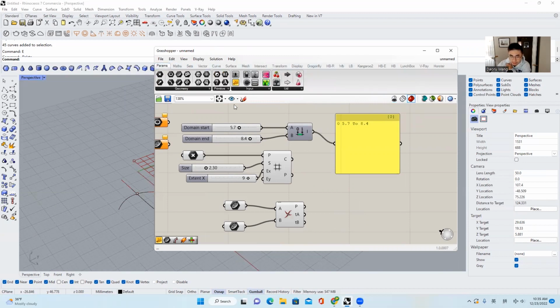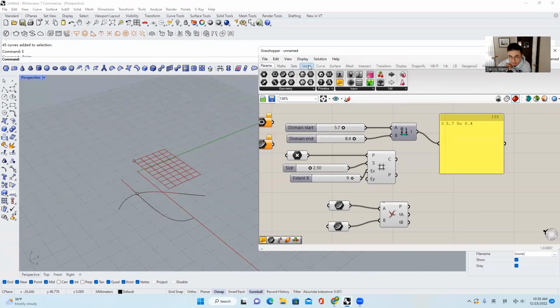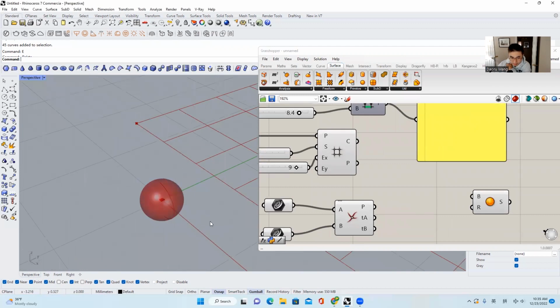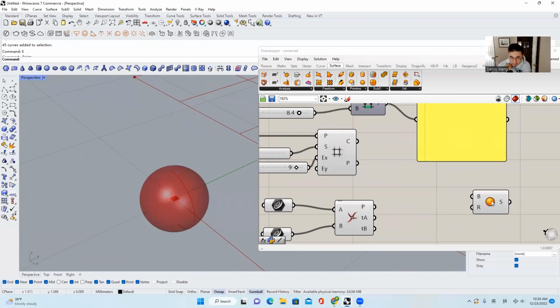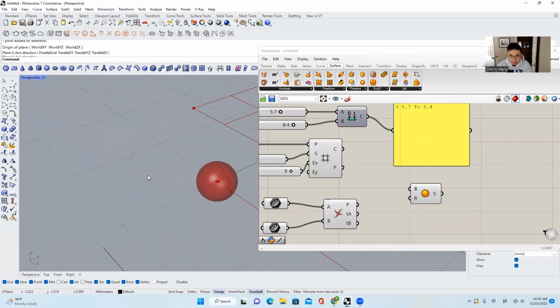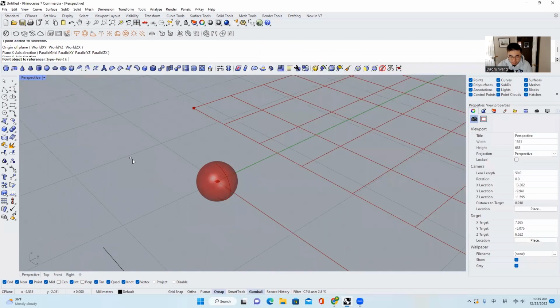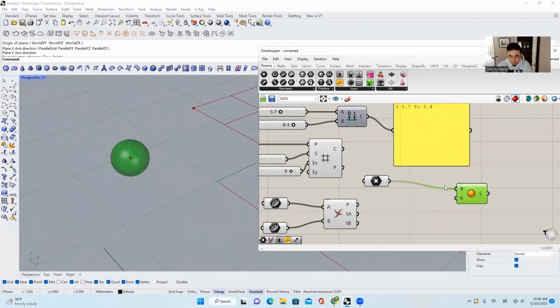The next thing I want to show you is this tab here. I will talk from the left, which is pretty straightforward. For example, let me make a sphere first, okay? I believe sphere is right here. You come over here again, and you can see that you can now select anything. If you highlight it, you select this one specifically, and the sphere will show in green in Grasshopper. If you want to change the center of this sphere, you can come over here, select new point and then drag it in. So you will move it here.